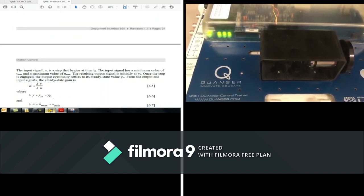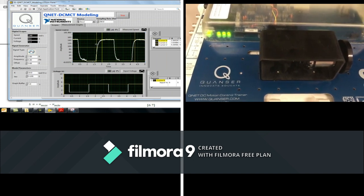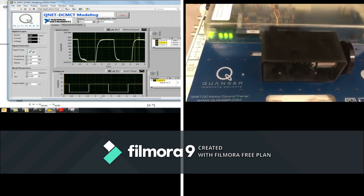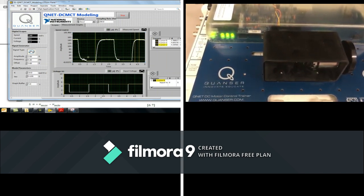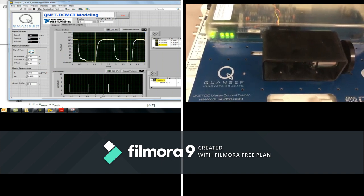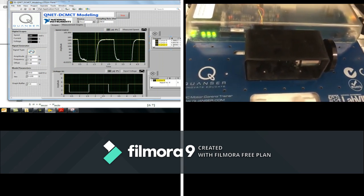So if we go back to our screen, I'm talking now about the y-axis. I select this cycle. This is T0, which is 1.56. In order to find the value of T1, I need to find it from the equation, which is approximately around 63% of that. So it will be around this value, and then I take my cursor to this intersection point, and I will say that it is 1.76 for T1,